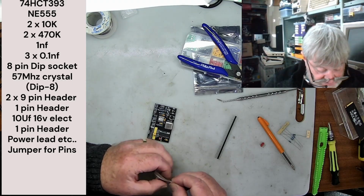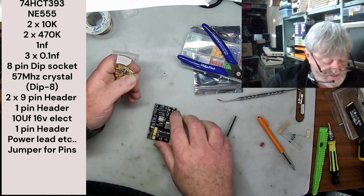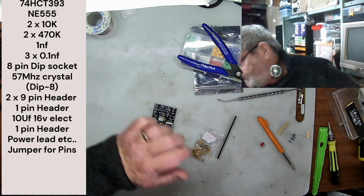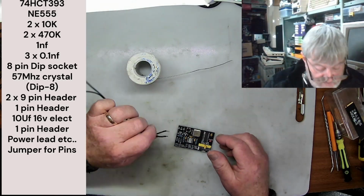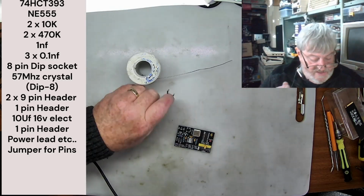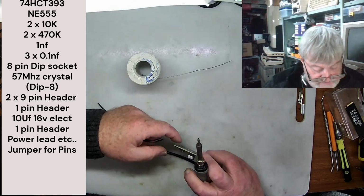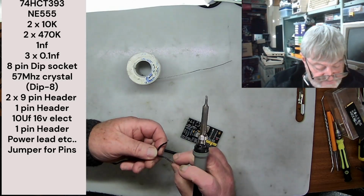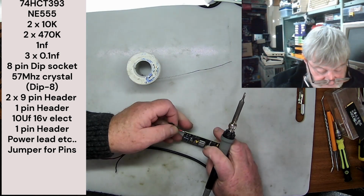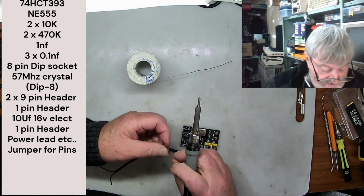So I will clear this lot away, and I'll find my piece of wire, or pieces of wire to go in for the power, and then we'll be back at this. Okay guys, so I got my bit of wire. So what I'm going to do is a little bit fatter than the holes. So the top plane of this is positive and the bottom plane is negative. So I'm going to solder them onto this one onto this top pin pad, and then I'm going to solder the other one to the bottom pad, which is the ground plane.